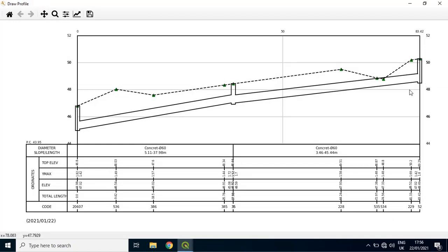The representation is a graphic type with a table of dimensions in the lower part. It shows the following data: elevation and maximum elevation of the manhole, Y max of the manhole, material and diameter, slope and length of conduits. Data from the connections that arrive to the conduits. Mention title and date.